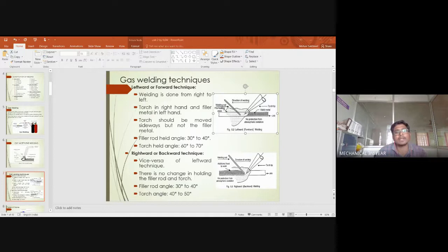And the inert gas may either be helium, argon, nitrogen, or CO2. The same kind of inert gas is used in MIG welding also. The current range is from 100 amps to 400 amps. This also may differ as per the thickness of the metal that is being joined. The welding torch may be either air or water cooled depending upon the current used.